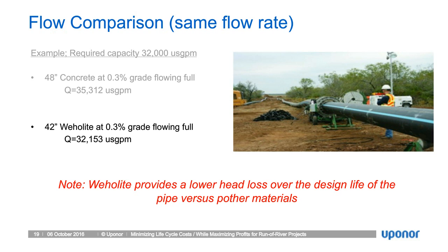The difference between the two, because of the installation, whether it's above or below ground, can mean significant savings in the overall project costs because we're using a smaller pipe. For burial, it could be less bedding material, a smaller trench width, and so on. So there could be material as well as labor savings in the total project.